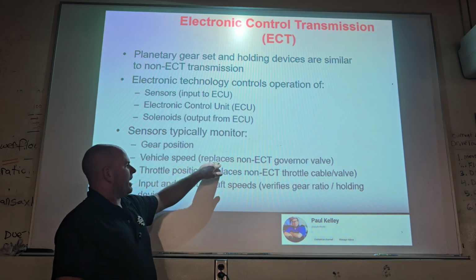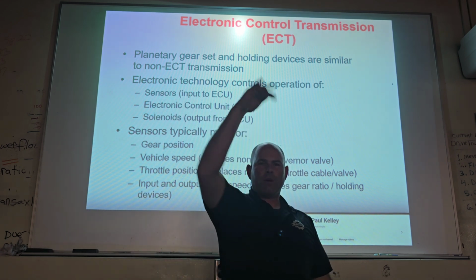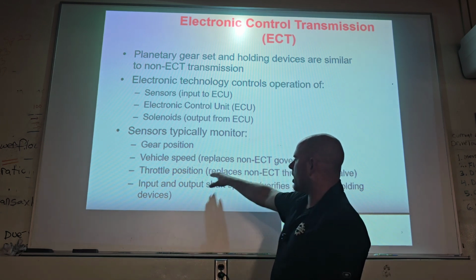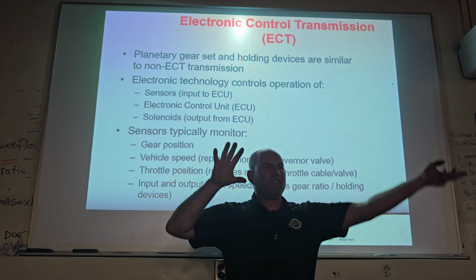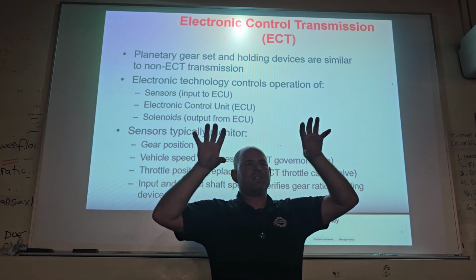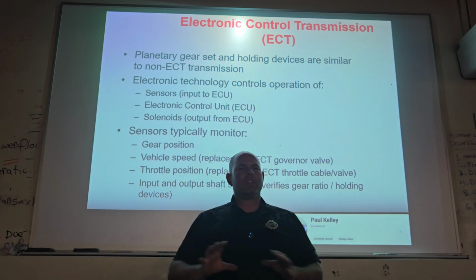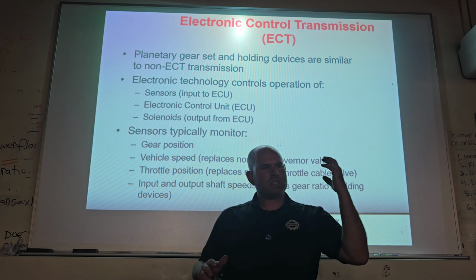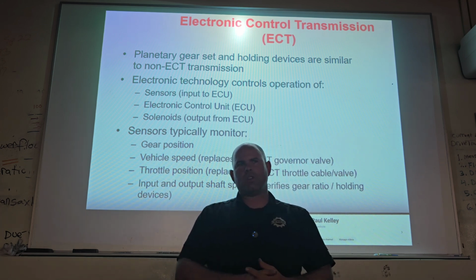So now you have the vehicle speed sensor that's indicating speed through waveform, and they're going to basically give that a score. And then you have throttle position, which is voltage, and they're going to basically give that a score. Eventually, your vehicle speed waveform will get a higher score than your throttle position, TPS, and it'll say, okay, give us an upshift. Those two never made pressure. There is no throttle pressure, do you understand? There is no governor pressure. All they do is compare their signals digitally.